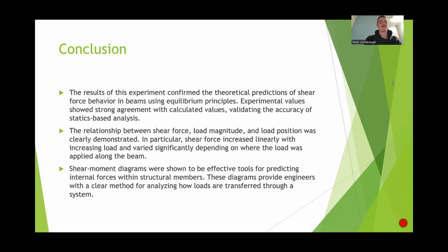In conclusion, the results of this experiment confirm the theoretical predictions of shear force behavior in beams using equilibrium principles. Experimental values showed strong agreement with calculated values, validating the accuracy of statics-based analysis. The relationship between shear force, load magnitude, and load position was clearly demonstrated. In particular, shear force increased linearly with increasing load and varied significantly depending on where the load was applied along the beam. Shear and moment diagrams were shown to be effective tools for predicting internal forces within structural members. These diagrams provide engineers with a clear method for analyzing how loads are transferred through a system.